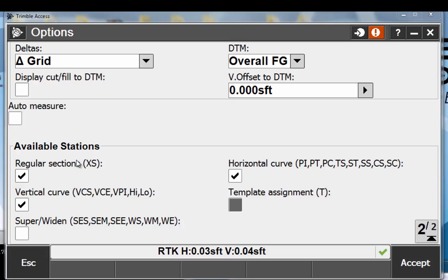And so what's calculated there, as best we could tell, the Trimble software is not taking the exact strings as I've defined or the feature lines as I've defined in the corridor in Civil 3D. It's recalculating that and it does it along target objects and everything. It's pretty intelligent as we found. So it's not just like an export of all those 3D lines and then you just stake along those lines. It's a little smarter than that. The best I can tell, it's ignoring that, and it's holding the geometry of the center line and what the specified offset is. Those offsets, it's actually doing the curve instead of the chord, from what we could tell.